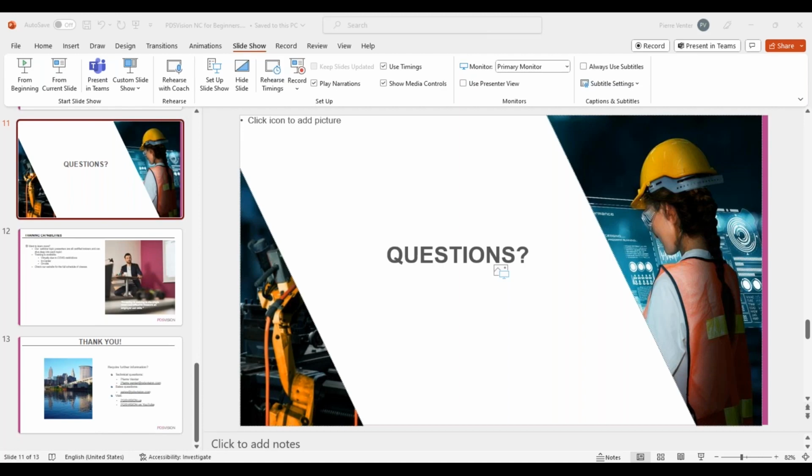Okay, so then we have a question about tolerances. Creo is going to use the geometry that's there. The tolerances come in with the machining that you apply. So the NC toolpath is not going to use that in any calculations.